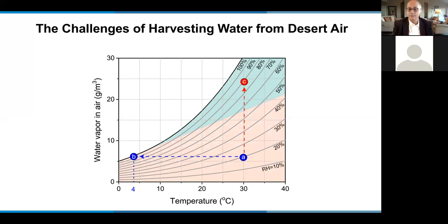then you would have, let's say in a closed device, you could create a humidity so that because the MOF can extract water from 20% relative humidity, it will eventually accumulate enough water to raise the humidity. So it's almost like taking, let's say, desert air and making it a tropical air, meaning increasing its humidity. Now, if I want to get the water out of this air, all I have to do is cool it down a few degrees, down to 26 degrees, to be able to get the water out. Much, much better prospect for extracting water from air in an economic way.